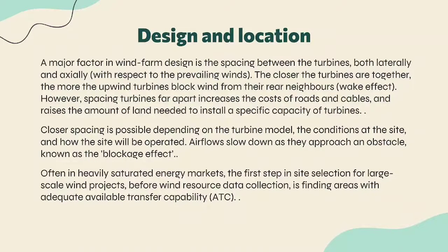Design and location. A major factor in wind farm design is the spacing between the turbines, both laterally and axially, with respect to the prevailing wind. The closer the turbines are together, the more the upwind turbines block wind from their neighbors. This is called the wake effect. However, spacing turbines far apart increases the cost of roads and cables and raises the amount of land needed to install a specific capacity of turbines. Closer spacing is possible depending on the turbine model, the conditions at the site, and how the site will be operated. Airflows slow down as they reach an obstacle, known as the blockage effect.